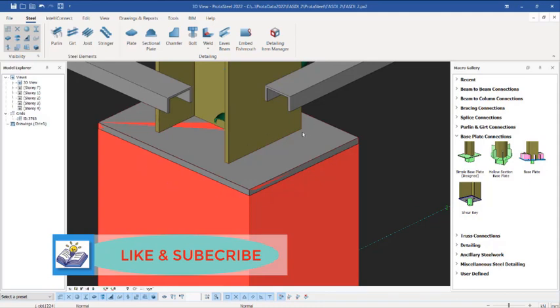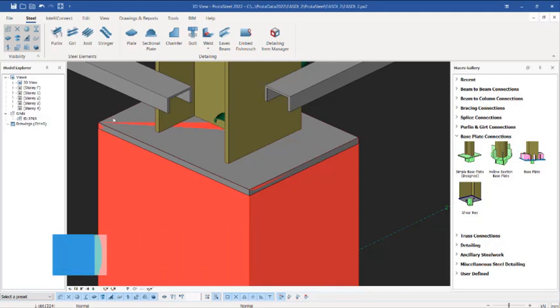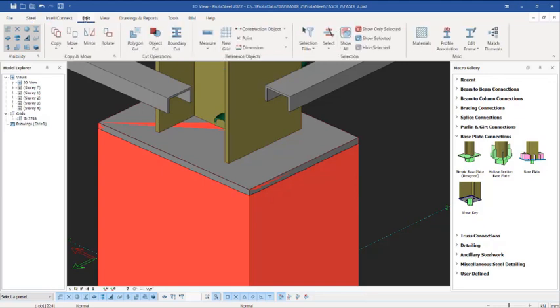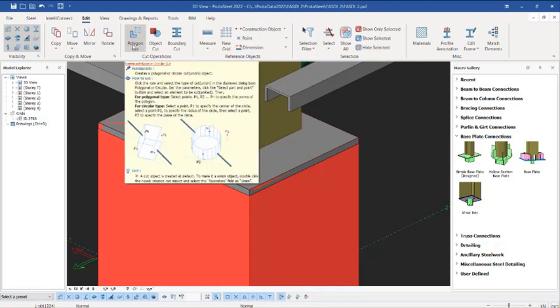So in this lesson, one of the things you also learn is how to cut off some part of this concrete so that we can free the plate itself from clashing with the reinforced concrete successfully. So how do we do that? We are going to be using the cutting tools. If you come to this edit provisions, you see various cutting tools here, but the one we'll be looking at is the polygon cut. So this polygon cut is what we are going to be considering.